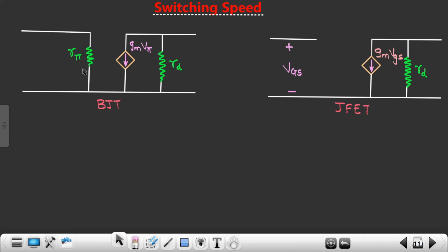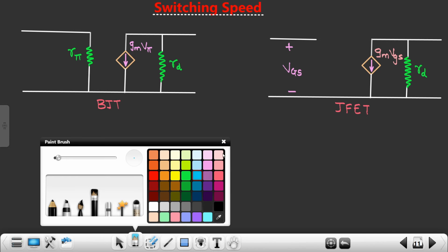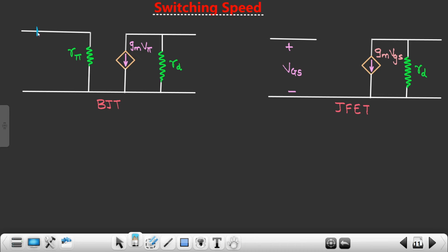Alright. So what we saw in case of BJTs was the input current IB controlling the output current IC, right? And over here the input voltage VGS is controlling the output current ID, or capital ID, you can write it that way as well, but generally during small signal analysis we prefer to write small letters only, okay.